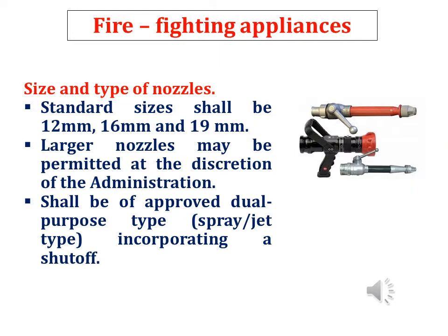Size and type of nozzles. Standard sizes shall be 12 mm, 16 mm and 19 mm. Larger nozzles may be permitted at the discretion of the administration. Nozzles shall be of approved dual-purpose type, spray/jet type, incorporating a shut-off.